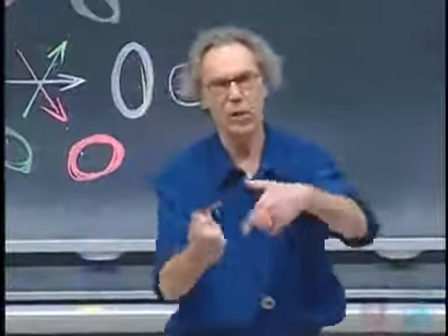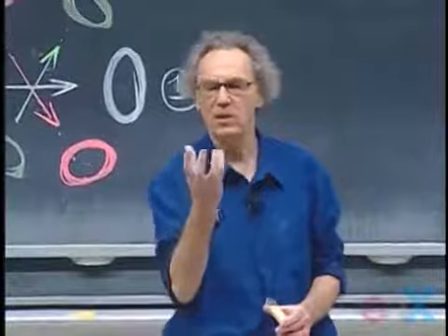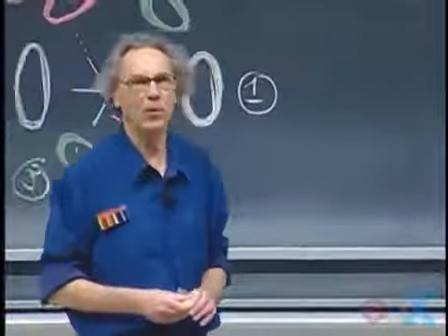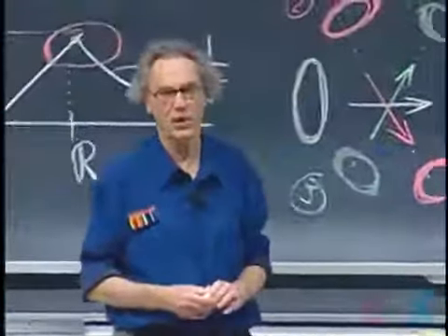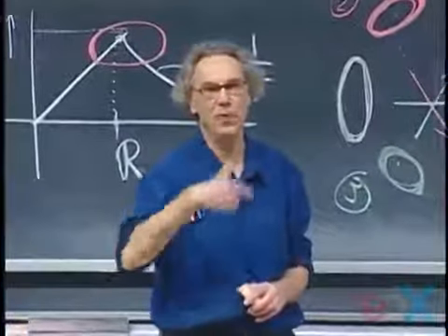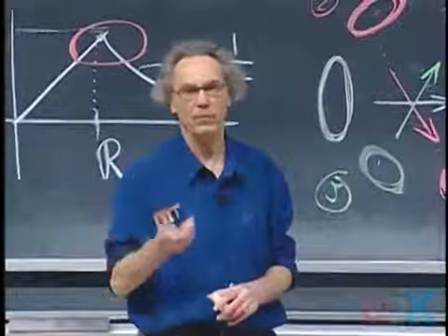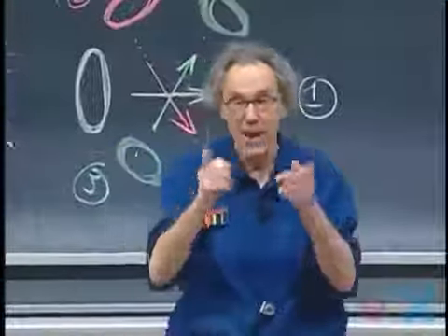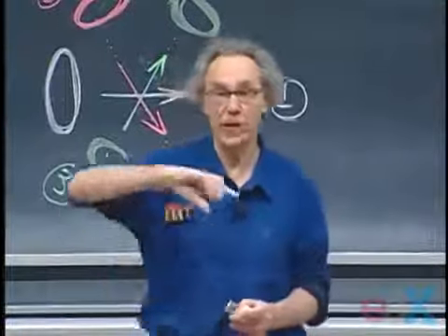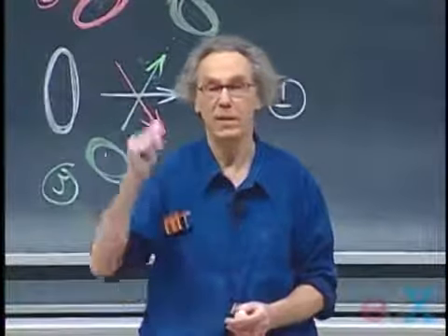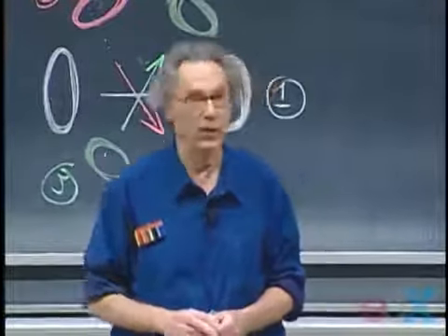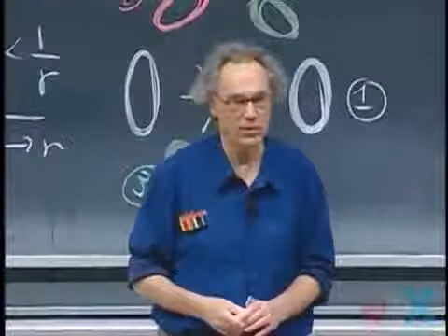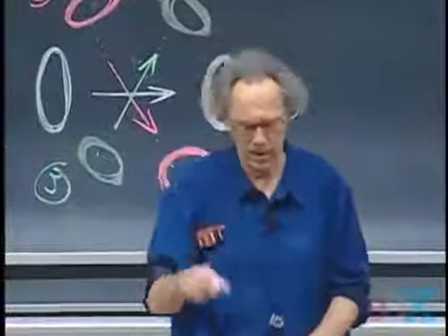How fast the induction motor will go depends on the conducting object. If it is a sphere, it will probably come very close to 60 Hertz, because a sphere has many possibilities for eddy currents to run around. Whereas if you take a ring, and we will try that, if you try to spin a ring in a rotating magnetic field, then of course the various paths that are available for eddy currents are very limited, can only go around in the ring.